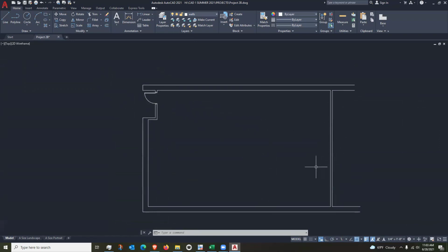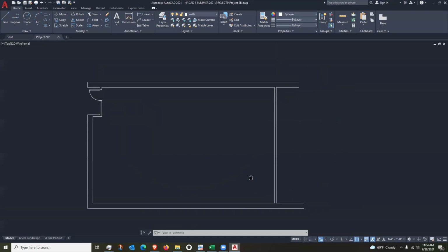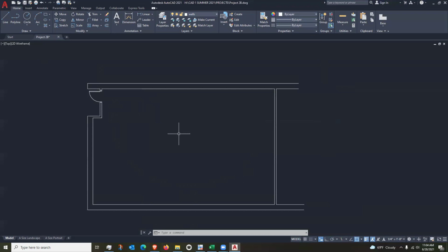And now I need to get those doors that are going into the back of the house. The first door is 8'10" from the corner of the room. I can do this a couple different ways, and what I'll do is turn on my object tracking or snap tracking.